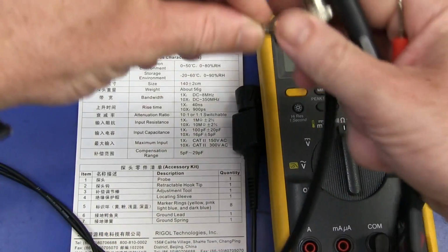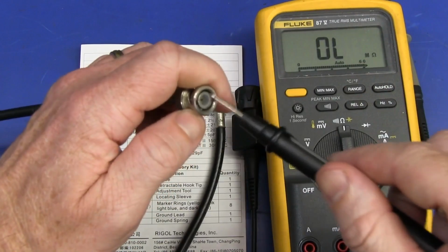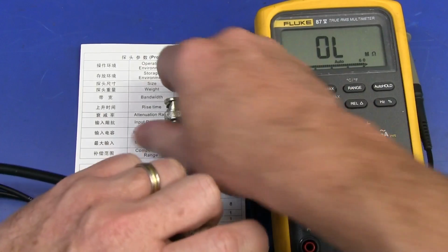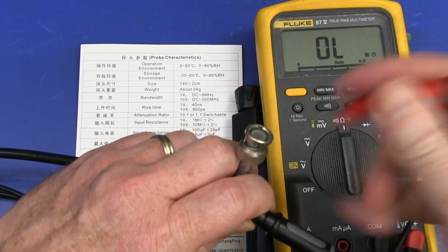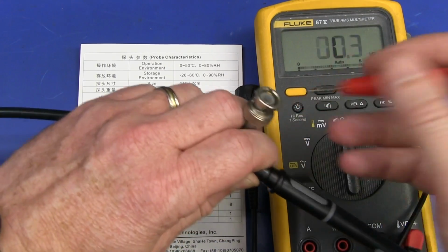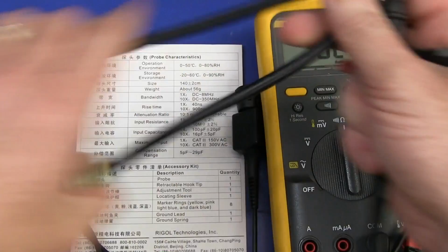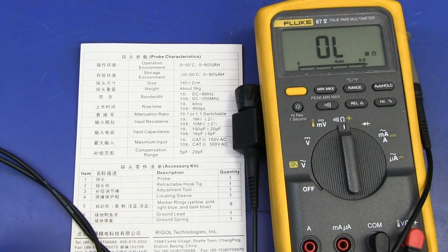Now, what we're going to do, we've got our regular coax here. It's just like 1/2 meter of coax, and we're going to measure the center conductor. And, well, no surprises what we're going to get here, folks. 0 ohms. There you go. It's a direct short because the coax just goes directly through. Yeah, it works as a transmission line and everything else, which we won't go into today.